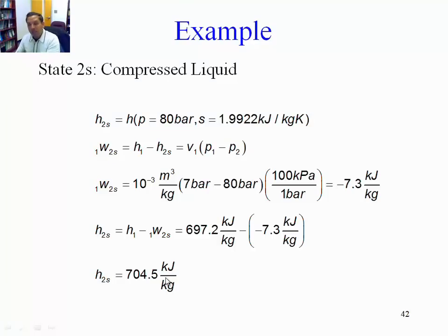Now in the example before, in the reheat example, or in the basic example, the enthalpy of the water going to the boiler was about 180. Now it's about 700. So it already goes into the boiler with certain enthalpy. That means that we don't have to invest that much fuel in order to heat it. That's the gain in the regenerative cycle.